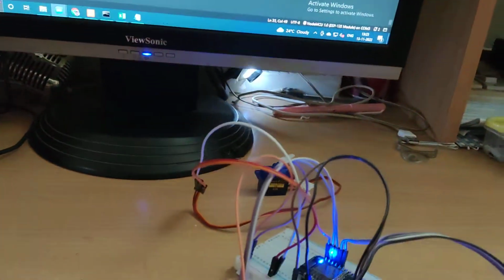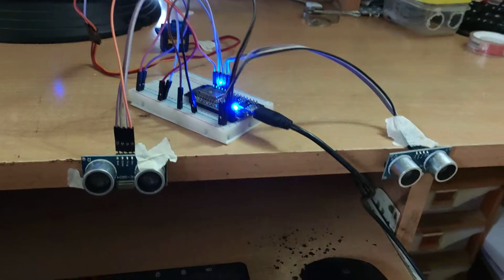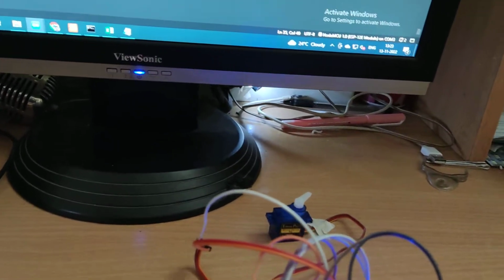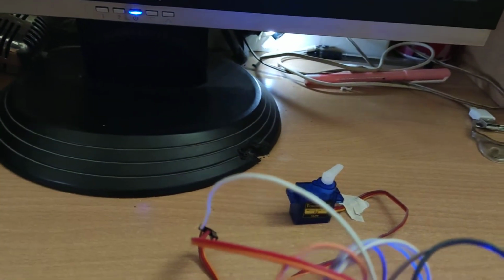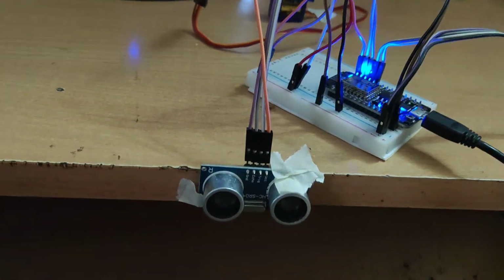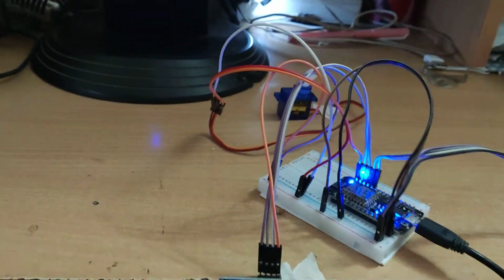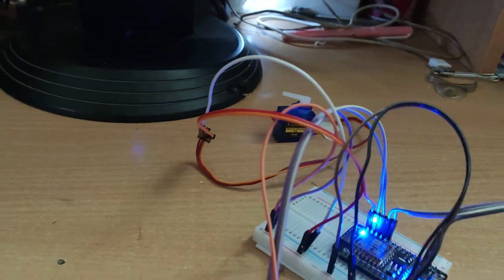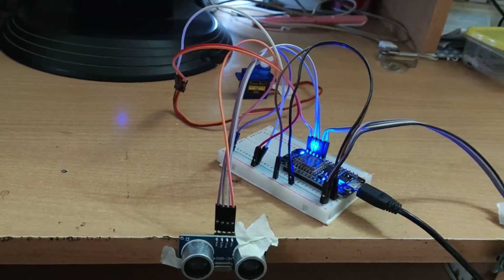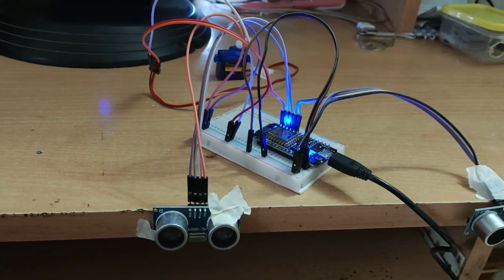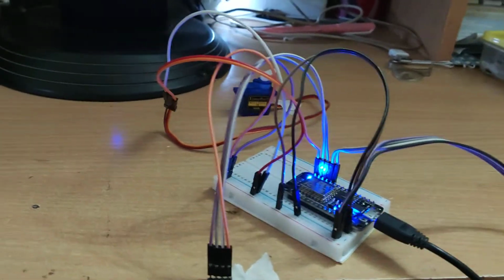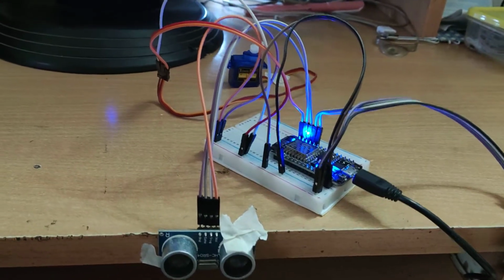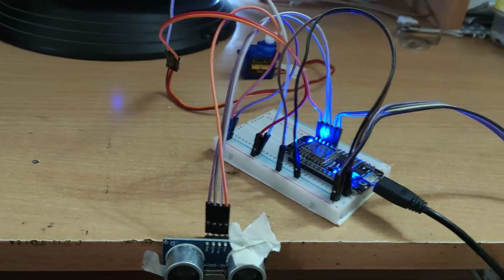So this is the way. It's a very simple logic. I'm comparing: if D1 distance is more than D2, turn the servo motor in the left direction. If D1 is less than D2, turn the servo motor in the right direction. That's a very simple logic, and we have put it in, but its application is very vast, and it's surprising how vehicles move without colliding with obstacles, taking safe directions. So this is the intelligence we have put in our IoT technologies.